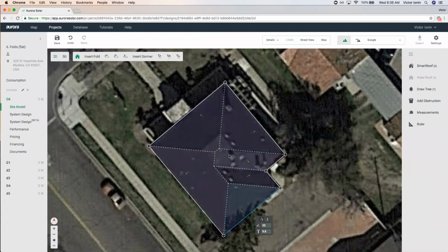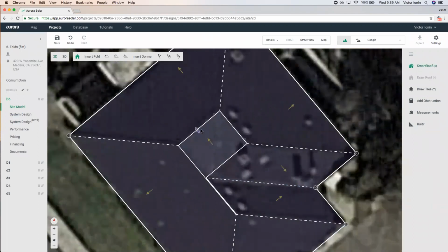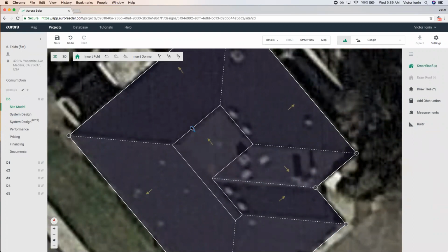It's flat. So what I'll do is I'll move up here to the top option, flat fold. Click on it, move your cursor over, and you can see it creates that flat top that I want. You can make it as big as you want or as little as you want. But when you're ready, you just click. Now, if you make a mistake and you want to readjust the fold, just click on the purple marker. Click and drag, and you can readjust it.